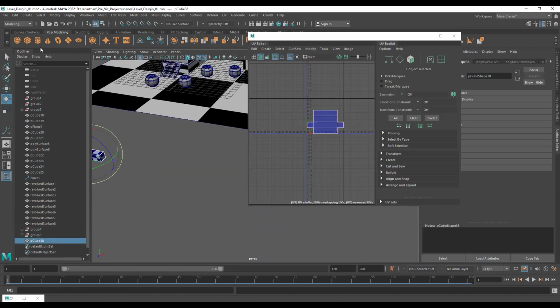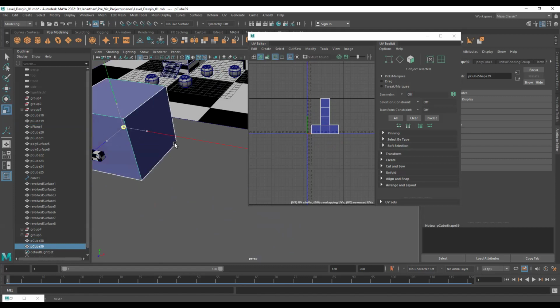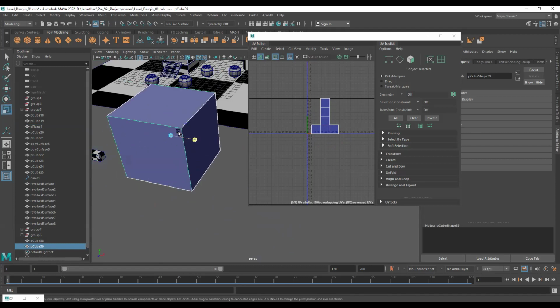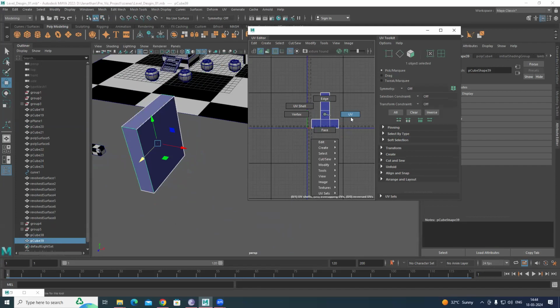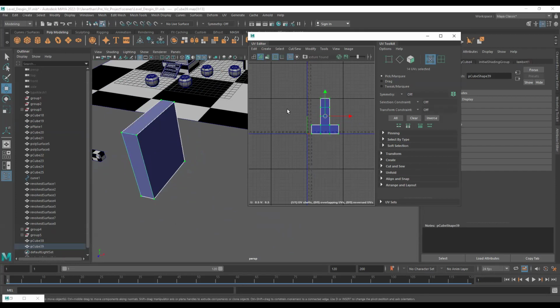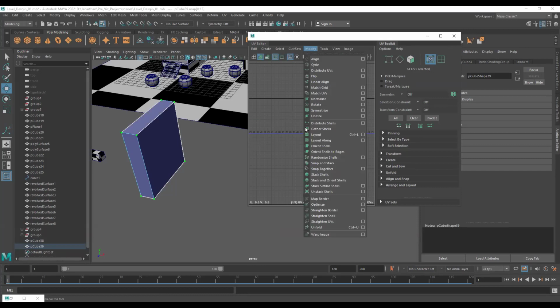Okay, can we do that again? I'll go for a box. Increasing this box as like this. Now I need to unwrap it. First thing first, select everything. So the method one, which we discussed before, select the face and project it the planar map. Yeah. Now unfold. In unfold, you can see modify unfold option box.